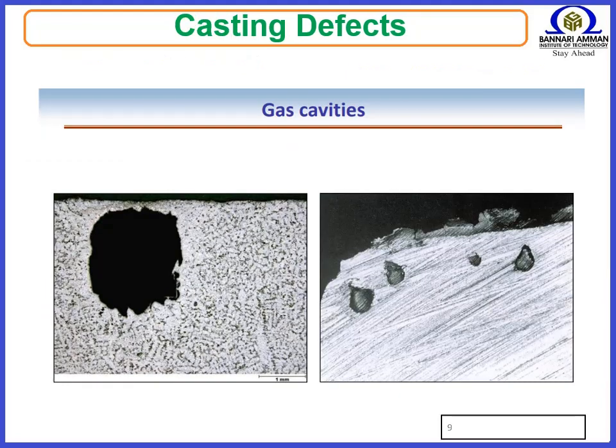Casting defects are: 1. Gas porosity, blowholes, open holes, pinholes. 2. Shrinkage defects, shrinkage cavity. 3. Mold material defects, cut and washes, swell, drops, metal penetration, rat tail. 4. Pouring metal defects, cold shut, misrun, slag inclusion. 5. Metallurgical defects, hot tears, hot spot.